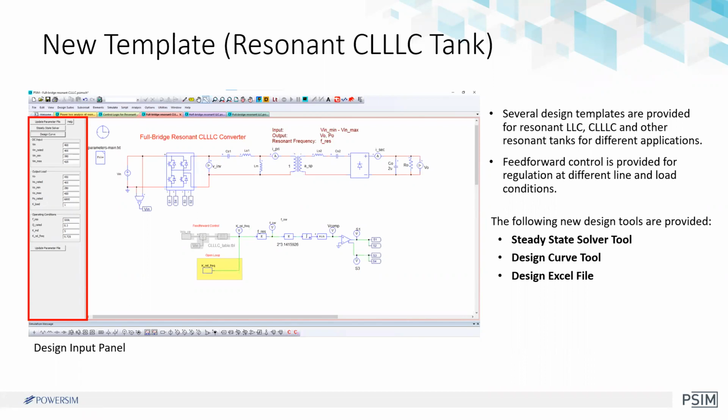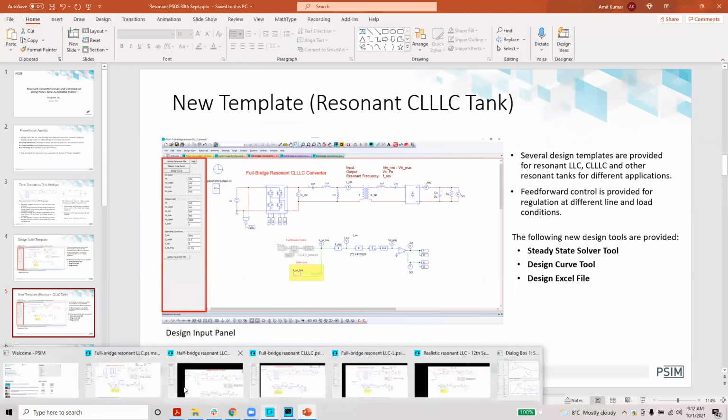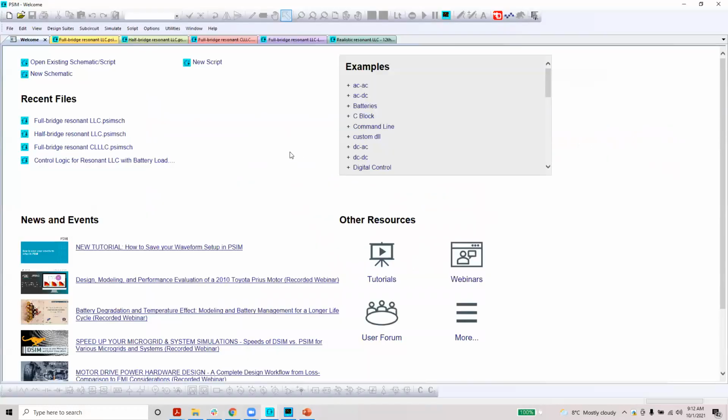And also you can utilize the parasitics of the transformer more efficiently using a higher order tank. So you can take into account a perfect T-shaped transformer to have this kind of a tank. So what I will do, I will go to the simulation and show you our tools in live action. So this is the welcome page of PSIM, right?